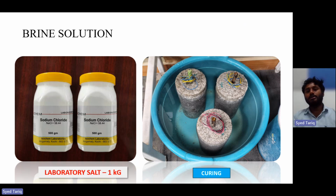Here also, in the same way, the whole setup is exposed to a chloride environment, made possible by adding laboratory sodium chloride salt at 3.5% concentration in the water. 75% immersion has been maintained after 28 days of curing.